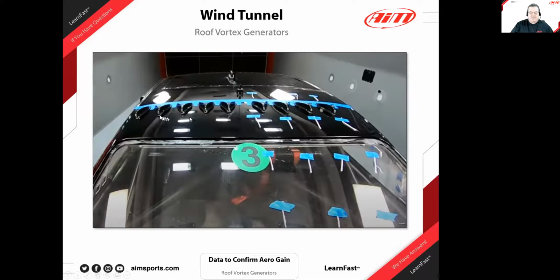So, vortex generators. You took a minute here towards the end of the run, it looks like, and you stuck these on there. What's the basic use you're trying to do? You're trying to get separation and not get the wind to drop down into that low pressure area? Vortex generators re-energize the boundary layer. So you can see as the air comes into those vortex generators, you'll get little vortexes coming off of it, which should help delay separation.